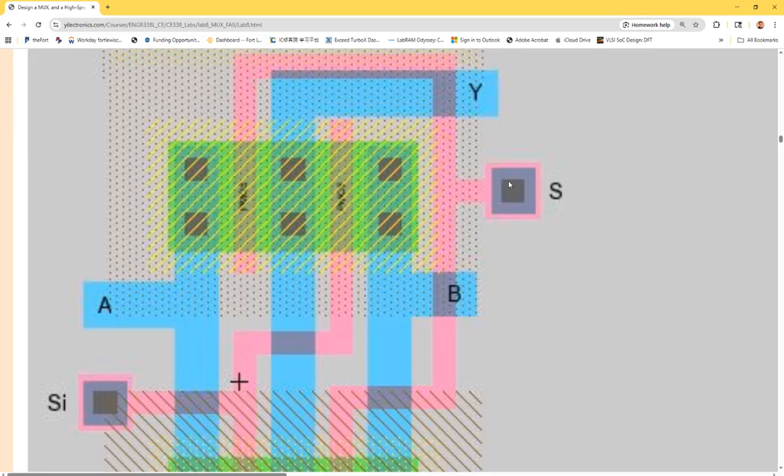So it's basically having a via, which is a little square here, and the bigger square is the actual metal one. But the thing is, if you place this, you can tell from this color, right? You place that light blue on the top of the pink, you're showing this color. So you can tell this is actually a metal one. The bigger square is metal one. So this little connector for poly, it's actually called a poly to metal one via.